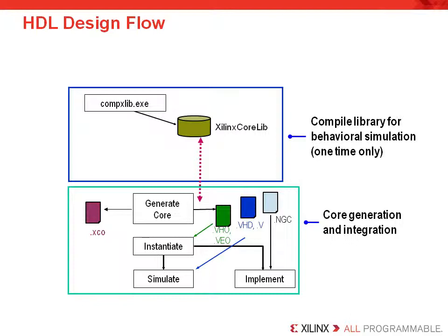This is only required once and is usually done once when a designer installs a new version of the ISE software. You should also note that if later on you install a new version of the code generator to get access to your newly available cores, this command will not have to be run again. All upgrades to CodeGen automatically install the new components' compiled behavioral model for simulation.